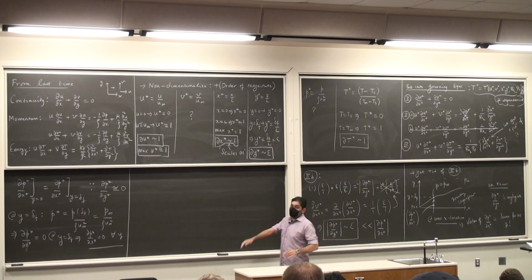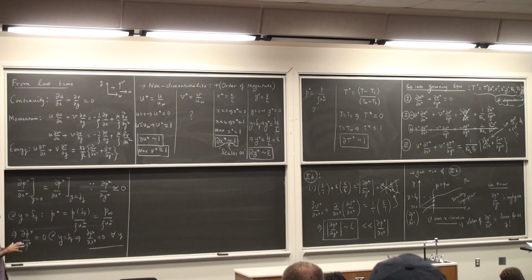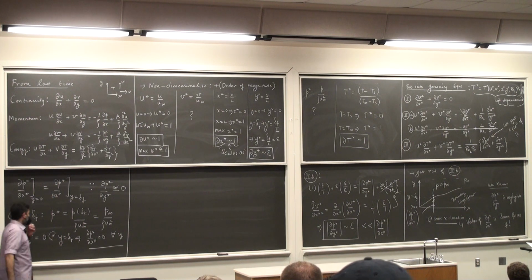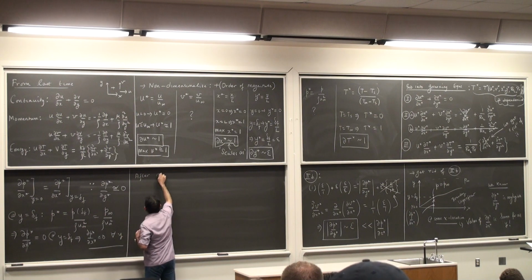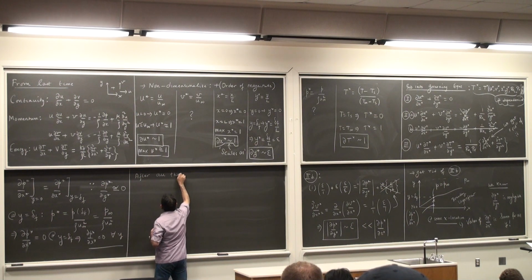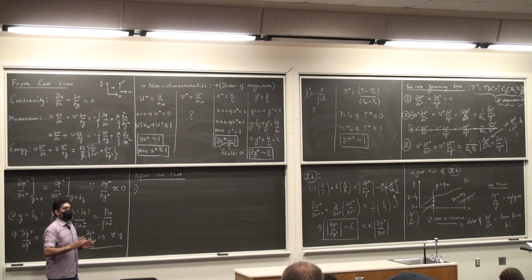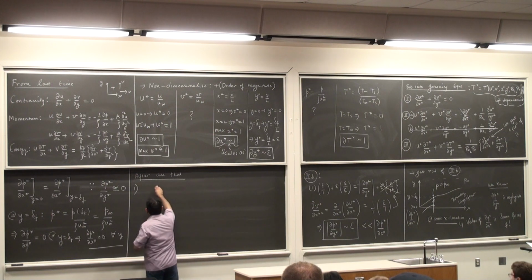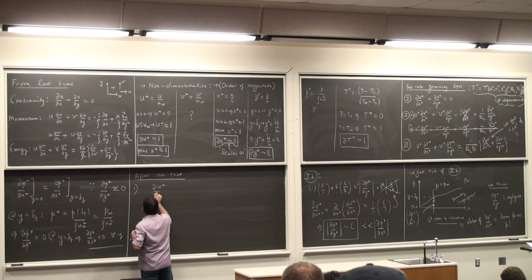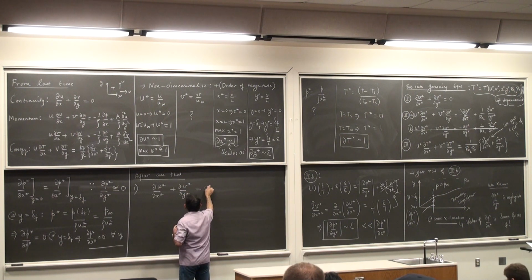And so the end of the story is almost approaching. And now our simplified equations are of the following form. So after all the simplifications, continuity is still there. You have to have it. Mass conservation has to be happening all the time. du star by dx star plus dv star by dy star is 0.